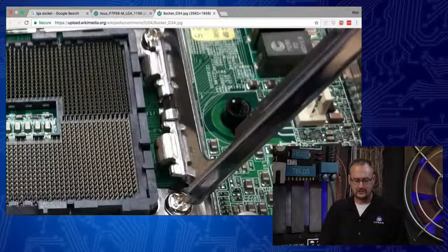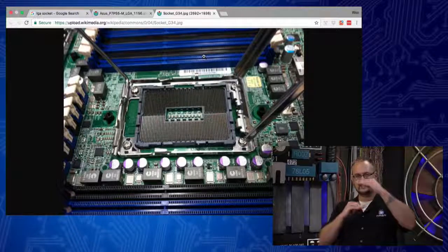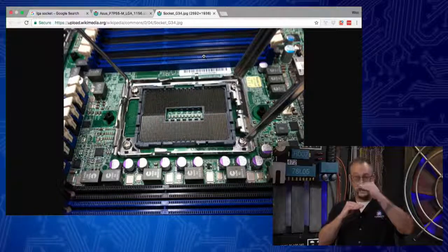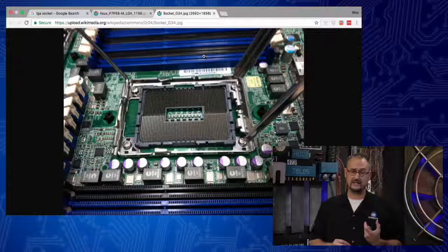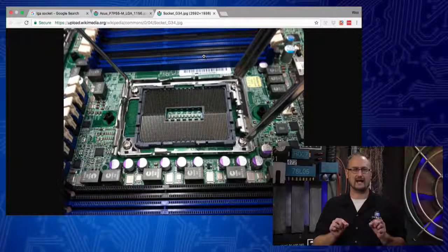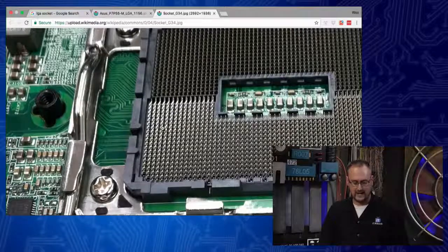You'll see a latch, and that latch folds down on top of the CPU, and then you pull this lever, and it takes the surface of that latch, the closing point there, and presses it down. Now, on the bottom of an Intel-based CPU, you just have these flat contacts, right? And the electrical contact is made with the pins, the grid array here that is in the socket.